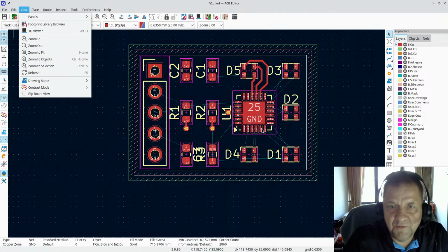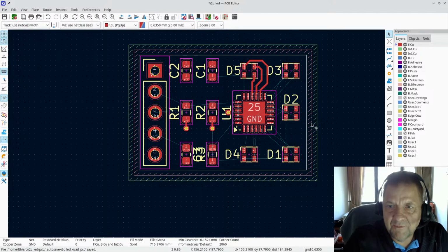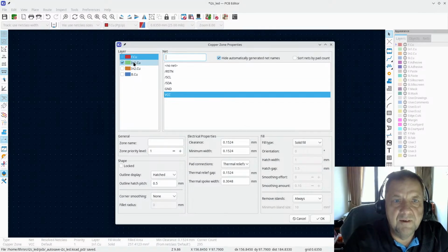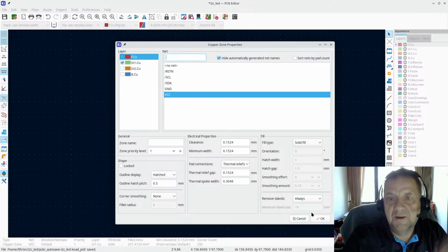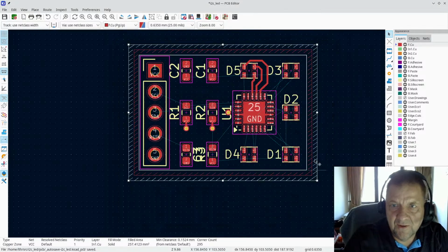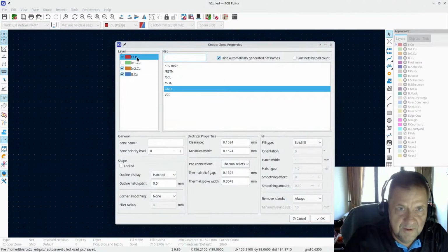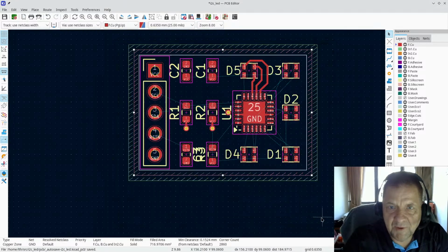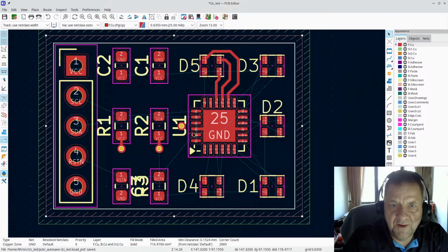Yesterday we did switch to a 4-layer board. I will have a ground fill on, no, that is the VCC layer, which is int1, the internal one layer. I will have the power supply there, and then on all the other layers, the top and the bottom and the int2, I will have a ground fill. It should give a pretty good ground plane, I think.